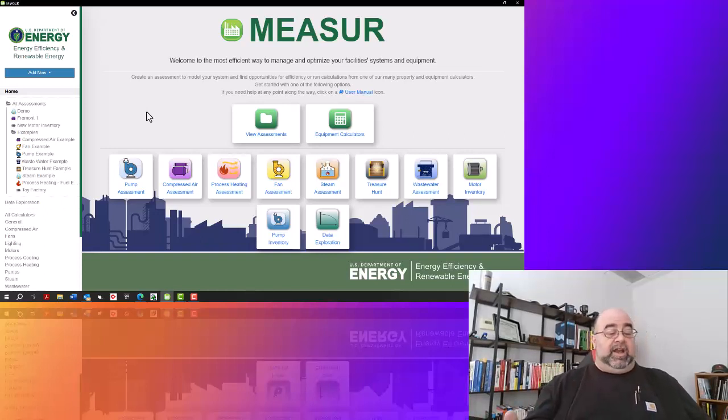So, doing an audit on compressed air, pre-audit, you monitor the power. I always say you want to monitor plant power overall, let alone the local power, because as you start making improvements, you want to measure and see if the improvements you're making are causing other things to occur. One of the things we found in the study was everything kind of impacts everything else. So when we would try to make a modification in one area, it's possible that another area has to compensate and energy costs actually go up. We found this also, believe it or not, in LED lighting. We were measuring incoming power, and we put in LED lighting. It's like, why did the energy cost go up? Well, it's because nobody filtered out all the additional harmonic content, which used energy.